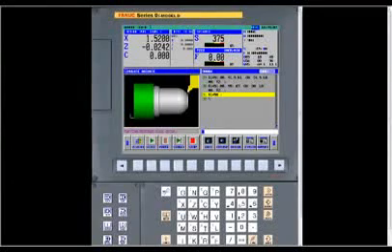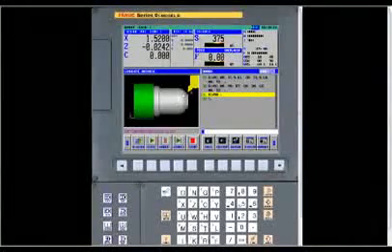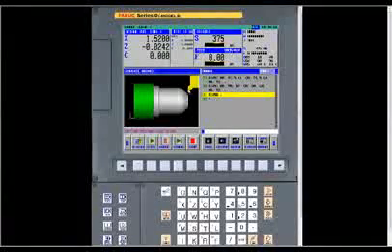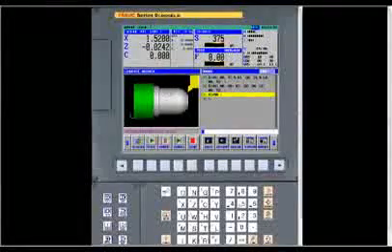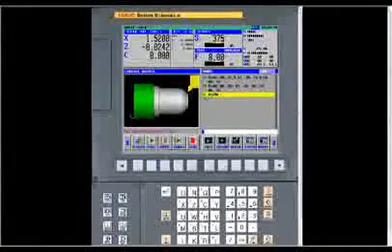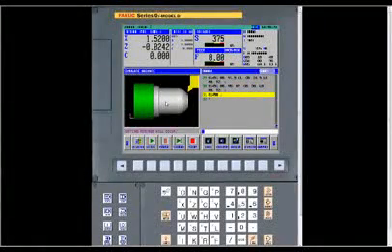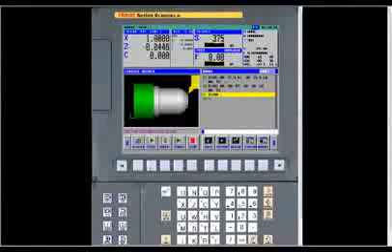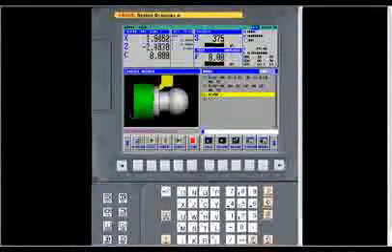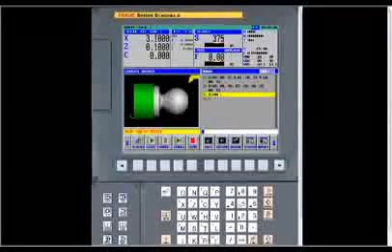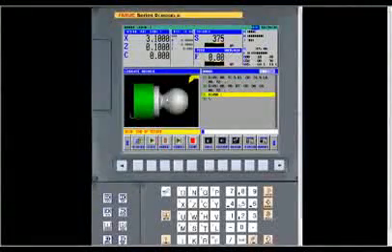It's a 55-degree tool with 3 degrees of lead on the front. And also, see how we're getting this message, cutting residue will occur. It's looking at the angle we described on this tool and saying that once it goes in and does the relief on the back side, that tool will not be able to get in there and cut all of it. But with this tool, it will only do what it can. So we'll start it again, and it'll finish what it can. You can see the geometry here is not exactly what we described, but it did whatever it could do with that tool.